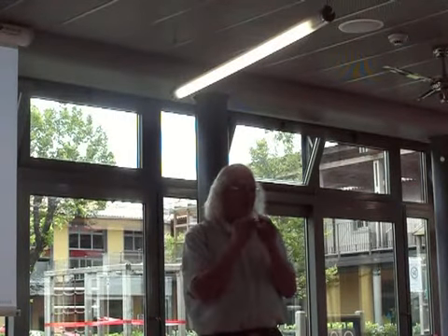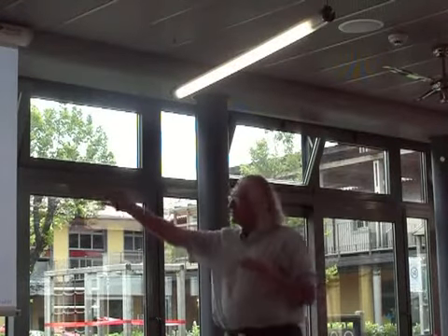Now, in the next few minutes, I hope to convince you that that's wrong. This is what I call the spreadsheet mentality. I take all of the data, I put it in a spreadsheet, and I calculate the correlation coefficient. And whichever theory has the highest correlation coefficient must be correct. So that's fine, but that means I can never use this theory to extrapolate outside the data. But if I have a loading situation for which I know the data, I don't need to do calculations. So the real value in any theory for fatigue or anything else is to be able to extrapolate outside the range of the data. What good is it to have a theory that you can't extrapolate outside the range of data? Right? And I want to convince you that this is a mistake.